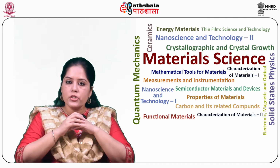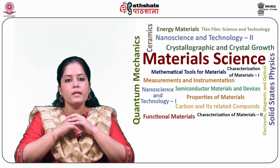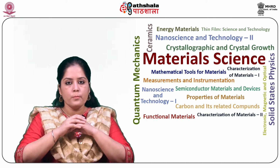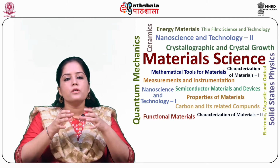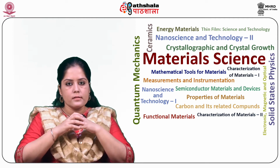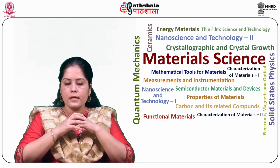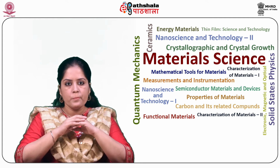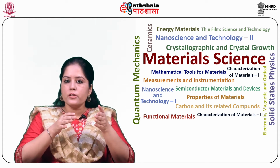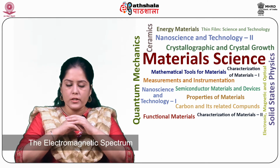Like the conventional optical lithography counterparts, extreme UV (EUV) lithography and X-ray lithography utilize photons to image the pattern on devices. But unlike their conventional optical counterparts, they utilize extremely short wavelength photons in the soft X-ray region for EUV lithography and hard X-ray for X-ray lithography regions of the electromagnetic spectrum.